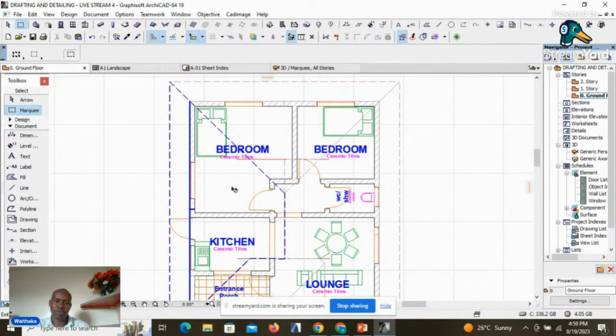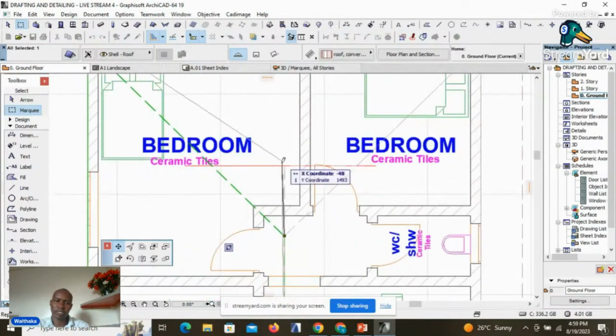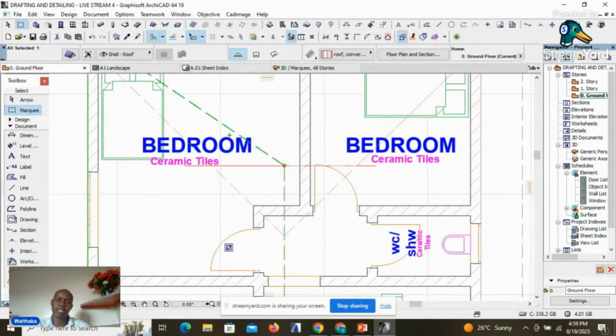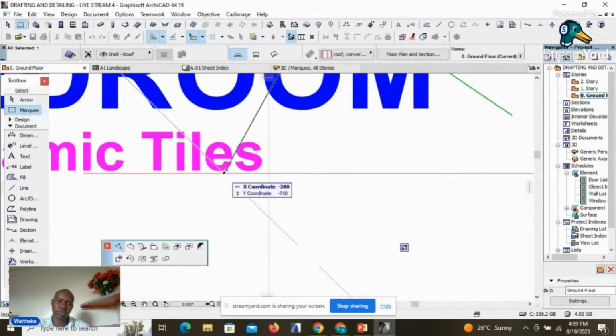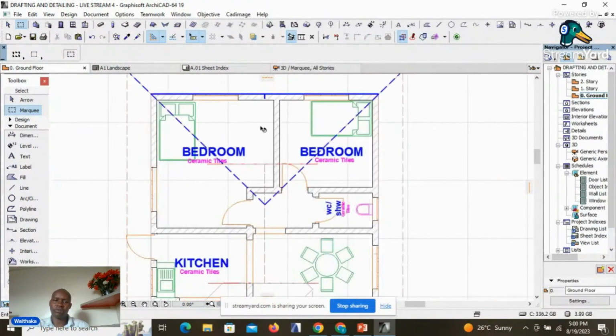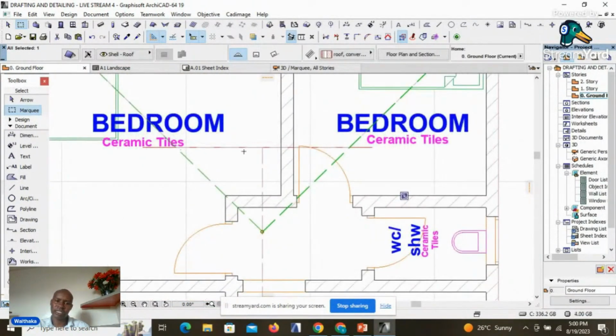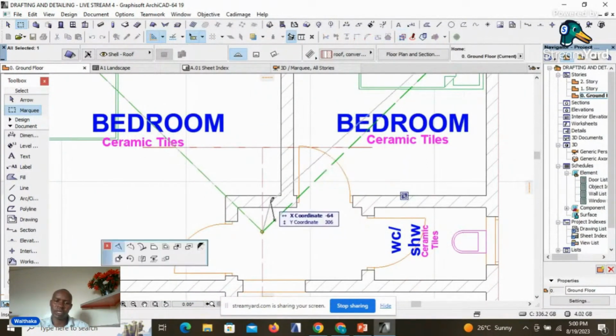So we do the same with this roof part. Click that node, stretch it up to that point, and then click on that edge, then introduce a node at that point, and then finally we are left with this part. Again, we can just deduct this part of roof, then we have accomplished our objective.